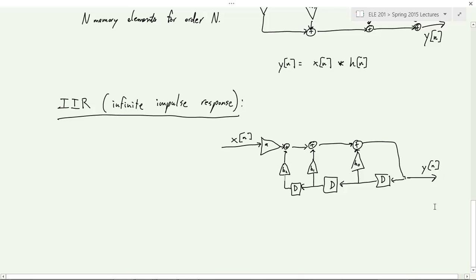But you've probably encountered this, some of you, in code, and not realized it's a filter. It's an LTI filter, and it's of this form. It's using feedback: the value you estimated it to be last time. In the simplest implementation, you just have one delay element. You look at the previous estimate, average it with your new incoming estimate, and make that your new output. The impulse response of this is infinite. So this gives you other designs.